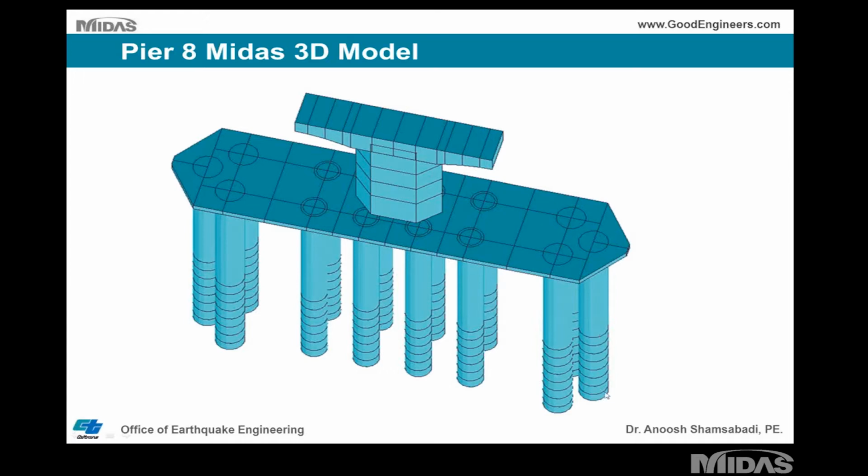As you can see here, the soil stops here, and then the remaining portion of the pile foundation system is cantilever with the pile cap and the superstructure. So the soil is where I have this circular line drawing. These are nodes representing the soil springs, which we will discuss later on.